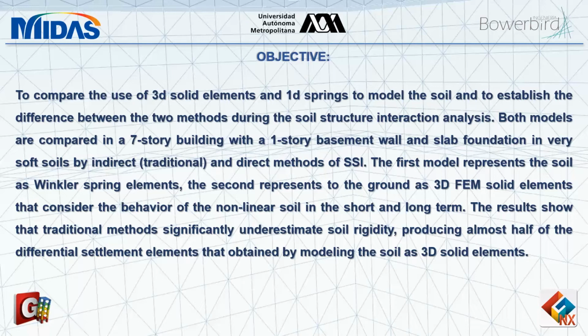As we mentioned, the soil for the structural model will be represented by Winkler spring elements, whereas in the geotech model, the soil will be represented by 3D cube or solid elements. And in both cases, the nonlinear behavior is limited to the specific limitations of each.